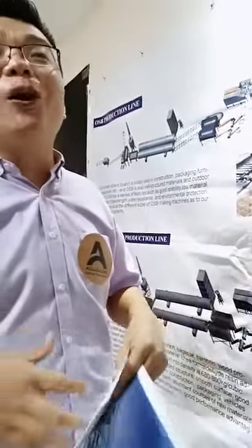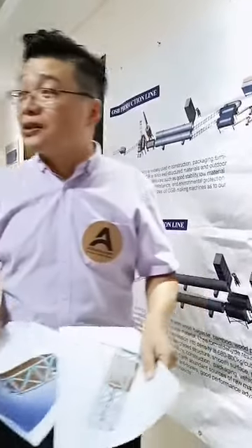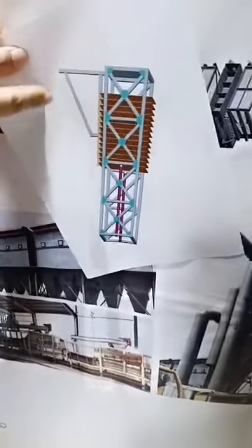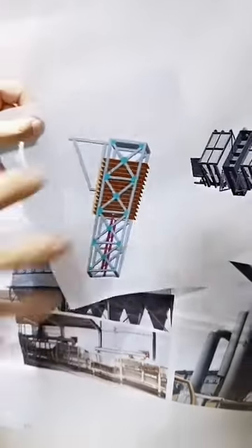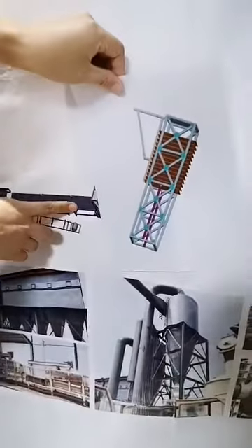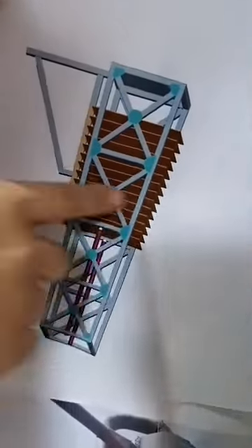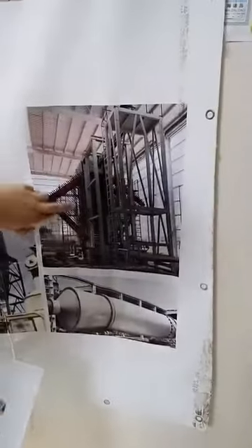Then the next one, the heart of the particleboard production line, is the hot press section. Now you see here, the first one is the loader. We call it the board loader. All of this is an automatic system. You can see from the belt, before loading there is acceleration to bring the boards to the loader one by one. Then it puts all the layers together into the hot press.